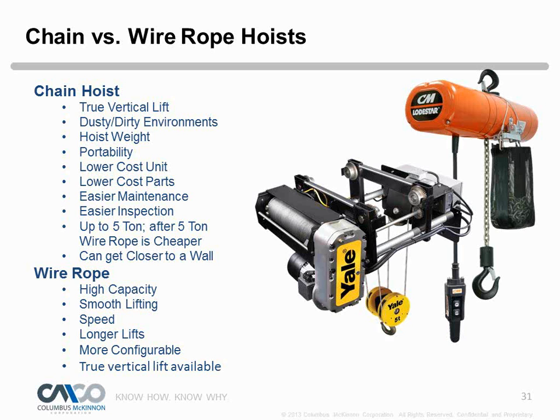Again, an air hoist wouldn't apply here. If we exceed that definition of an H4, we need something that exceeds it, and we may consider an air hoist for our lift because we don't have heat generation. With electric hoists, we're generating heat from the electricity and the movement, and air hoists are not going to get as hot, so we can exceed that H4. They really don't have that H4 rating. We call it continuous duty on an air hoist.